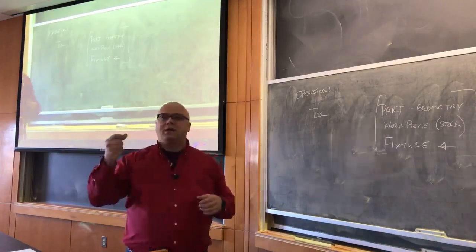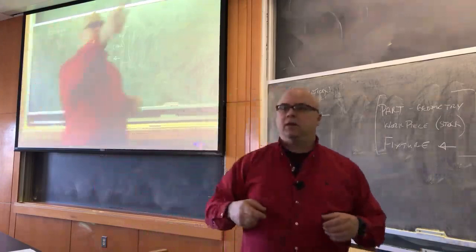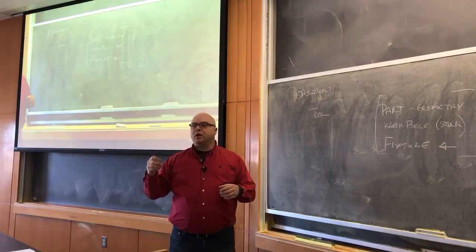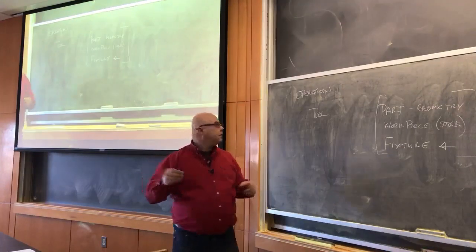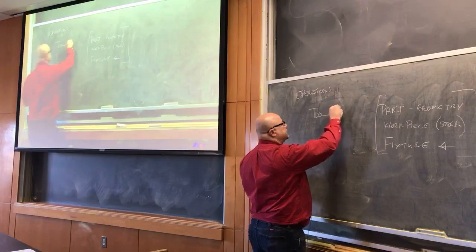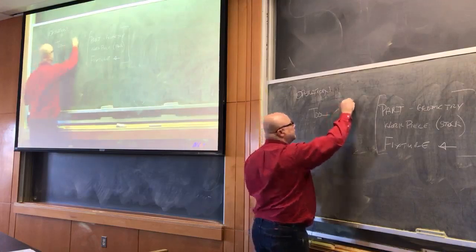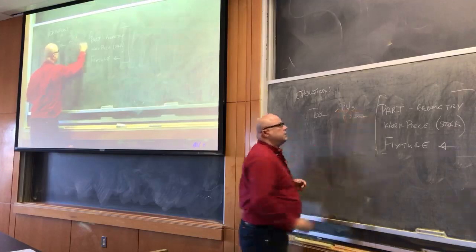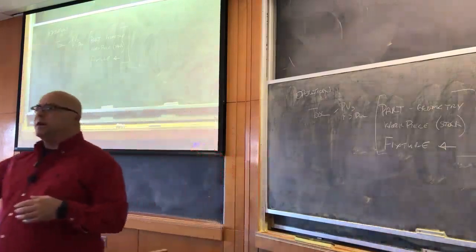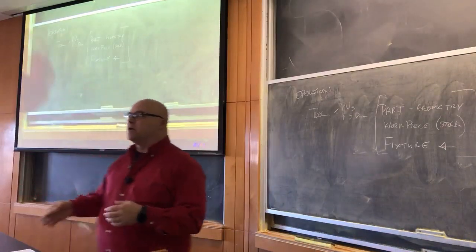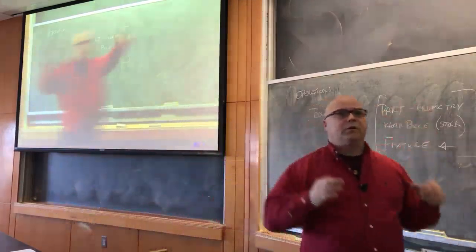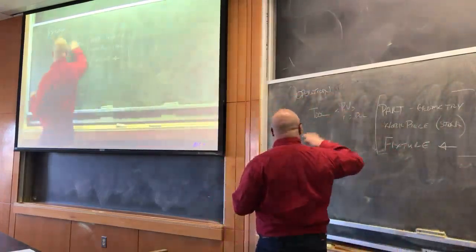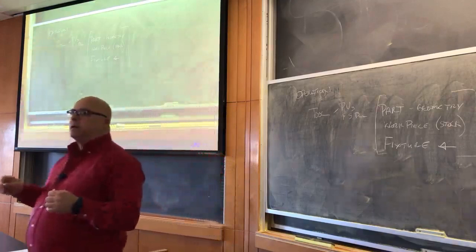What else do we know automatically once we've chosen the tool? Yeah. We don't know the offset until we put it in the machine. But we do know what's the correct feed, speed, depth of cut, right? We know the process variables because they're determined by the tool. So we know feed, speed, depth of cut. And we know that because the tool manufacturer provides us with that information. We've looked it up on some other chart, or we've experimented with this tool and we know what feed, speed, depth of cut to use for that tool. All right, so once we've got the tool, process variables, feed, speed, depth of cut, what's the next thing we're going to do?